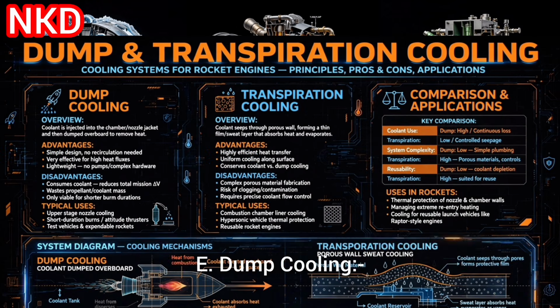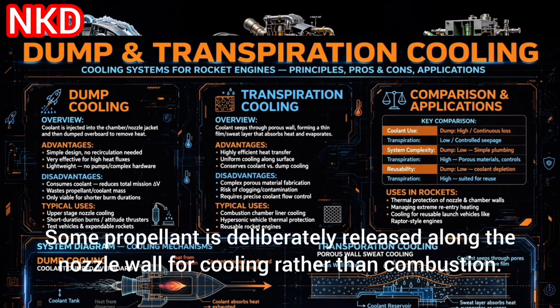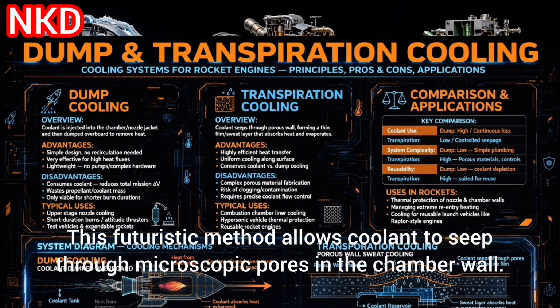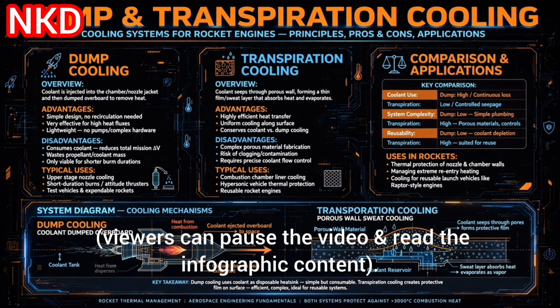E. Dump cooling. Some propellant is deliberately released along the nozzle wall for cooling rather than combustion. F. Transpiration cooling. This futuristic method allows coolant to seep through microscopic pores in the chamber wall. Viewers can pause the video and read the infographic content.